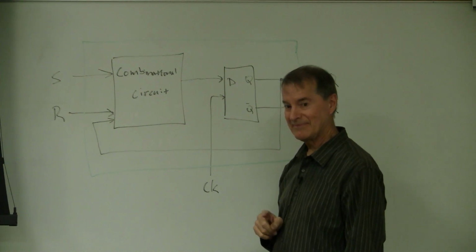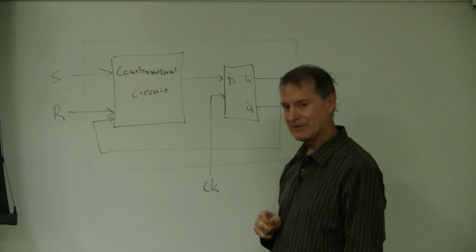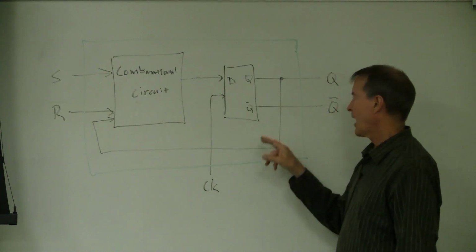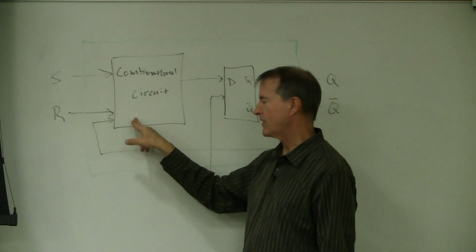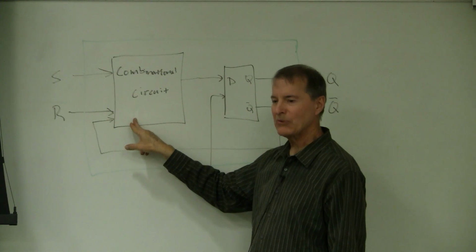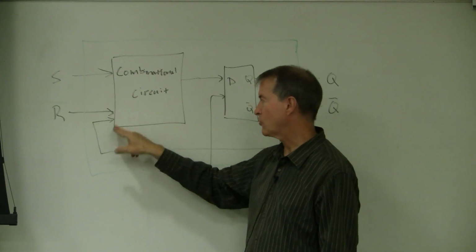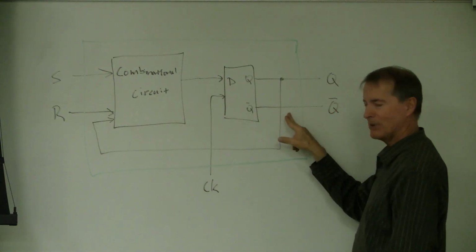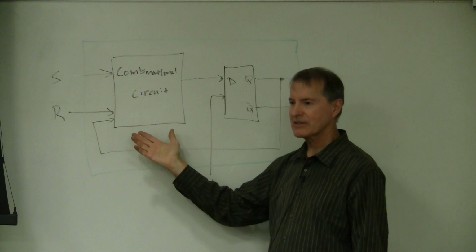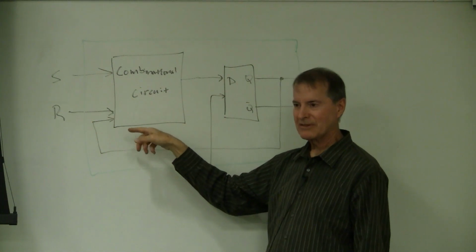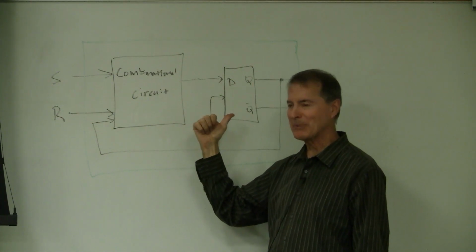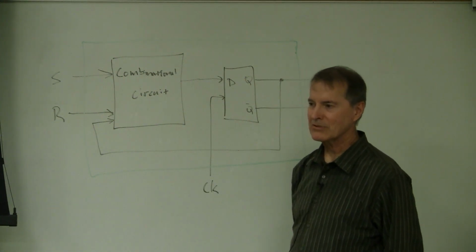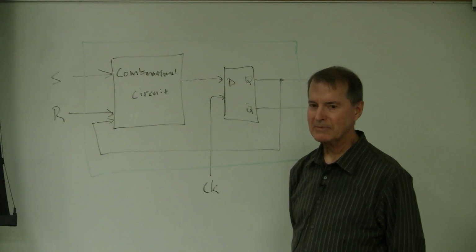Yeah, my other question is, in my circuits, I drew a line. Can we use the Q bar output? Absolutely. I only drew this Q feeding back to here, but it would be wasteful to have the Q coming back and then putting an inverter if you needed the Q bar, because we have it automatically from here. Okay. So even though we analyze it as 3 inputs, it's okay to use the Q bar as another input because it's always just the inverse of Q anyway. Okay. Those are good questions. Any more? Any other questions?